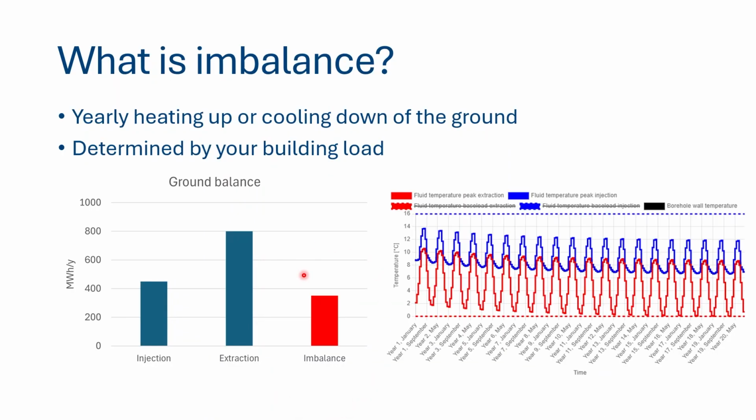And this imbalance causes a temperature drift in the long term of your borefield. So in this case, our borefield cools down year after year until we reach our minimum design threshold of 0 degrees in the 20th year.